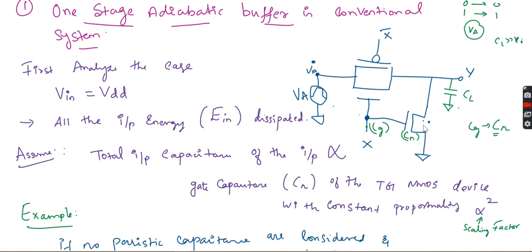As you know, when x is equal to 1, then this capacitor will be on, then the transmission gate will also be on. Slowly, when you increase this, it will charge your capacitor, but by that time, since this is also on, it may get discharged. There will be some problem. That is why we need to go for some other technique.